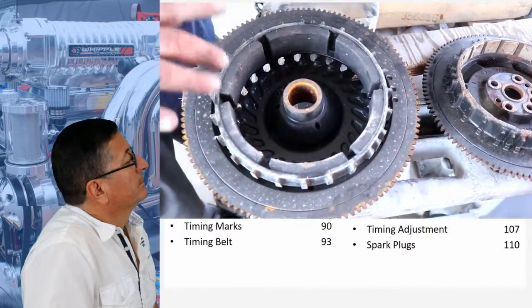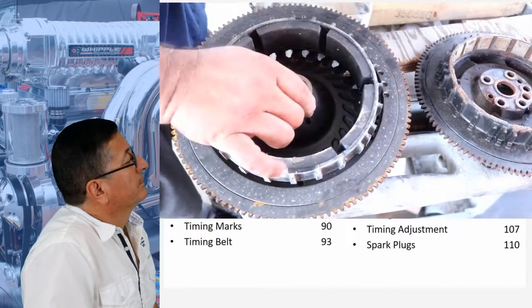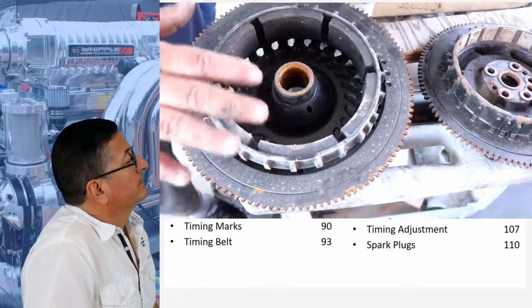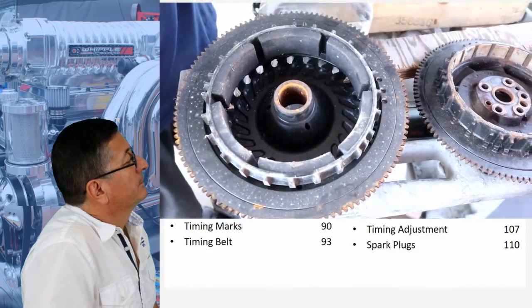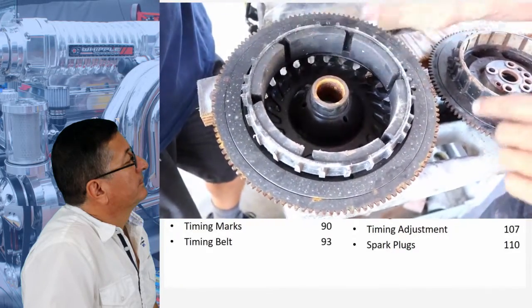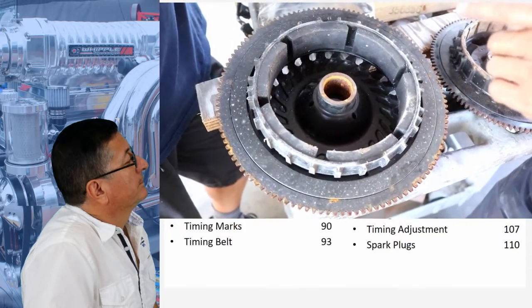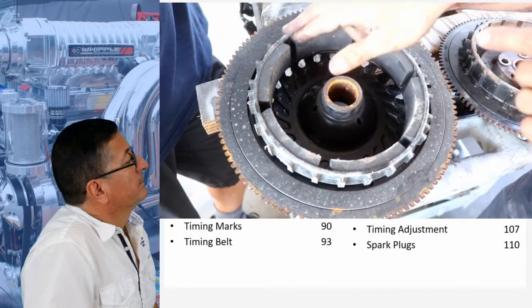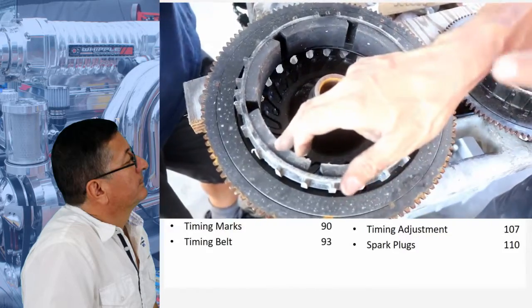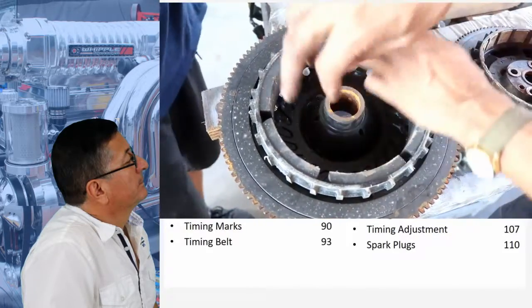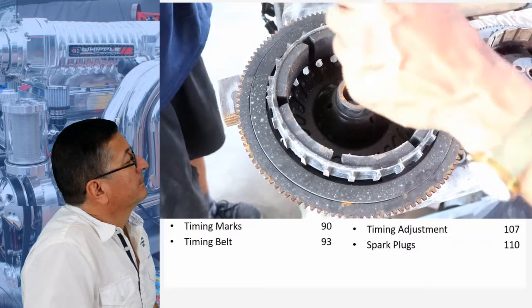Yes, you can replace these, but you have to be careful. There's an inner magnet inside here. If it spins out, you can't repair it. The flywheel's done. In other words, if you replace those magnets, you need to be careful with the polarity, because this one should be positive, negative, positive, negative, positive, negative. If you replace this one with a negative, you change the timing order. Correct.